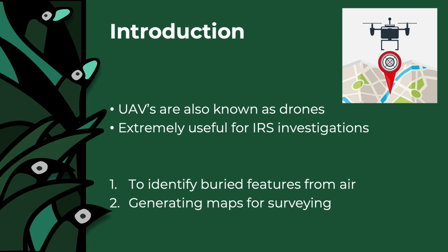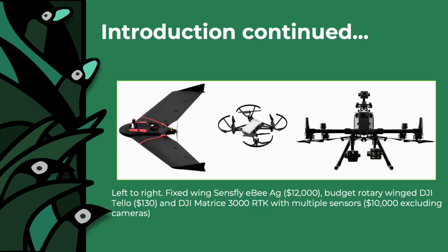There are many UAV options on the market that range in price from a few $100s for a simple quadcopter with camera, typically used for recreational purposes, to fully integrated multi-sensor systems costing over $20,000 that are used in the surveying industry. The level of accuracy and resolution will vary considerably between systems, so it is important to understand some of the basic differences. Choosing the right system will depend on your survey goals.